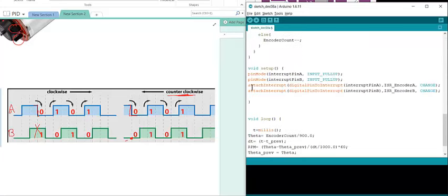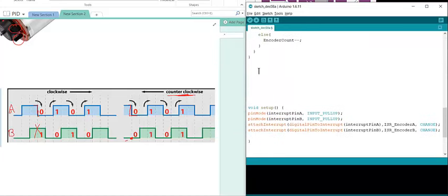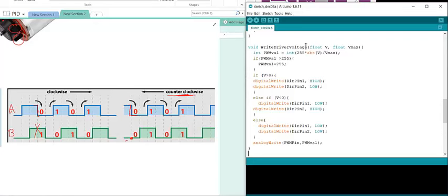And now we'll write our motor driver function just above the setup function. You see our motor driver has two input variables, the voltage and the voltage max. We need the voltage max to map the PWM so we can control the speed accordingly. We're using 8-bit, so 255, and that gets mapped to 6 volts. And there's some logic behind it.